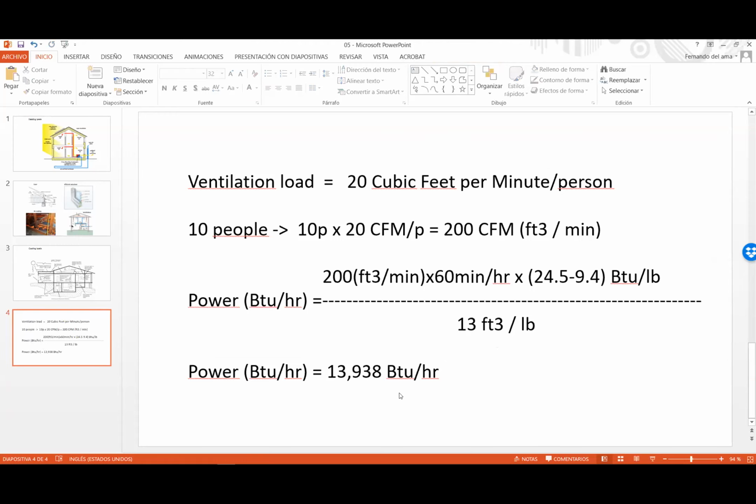Okay, so if we go to the Home Depot, I want a burner. Okay, what burner? First decision, what you want to burn? Oil, gas, pellets, wood, coal. So the first decision is what kind of fuel you want to burn. Okay, we see that pellets are a good option. Condenser gas boilers, it's another good option. And the second is what is the size of your burner? Okay, and the size is not the physical size, it's the power.